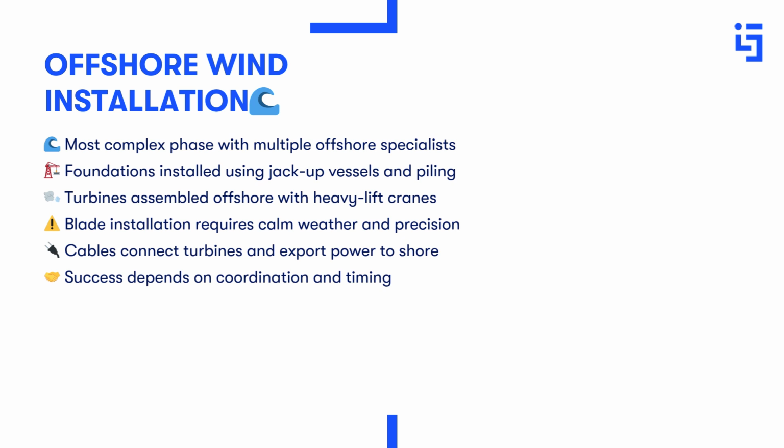The sequence begins with foundation installation. Specialized jack-up vessels position structures on the seabed using pile driving for monopiles or more complex methods for jacket and floating foundations. Precision is critical for long-term stability, while noise reduction measures help limit environmental impact.